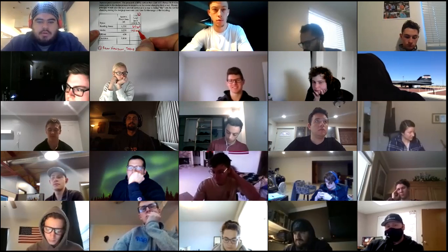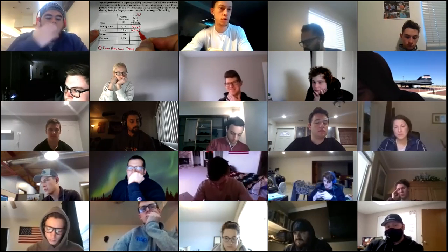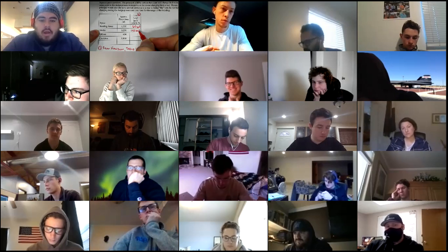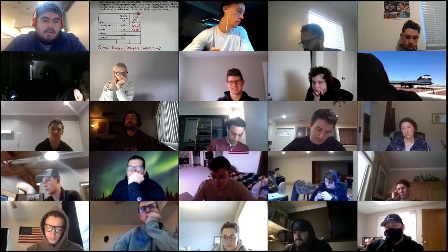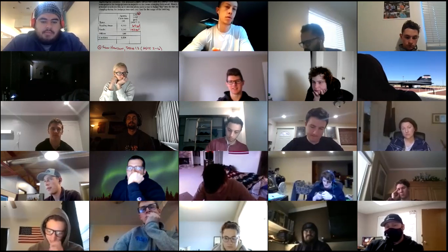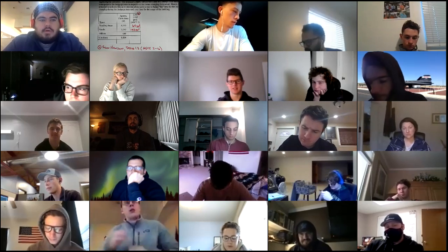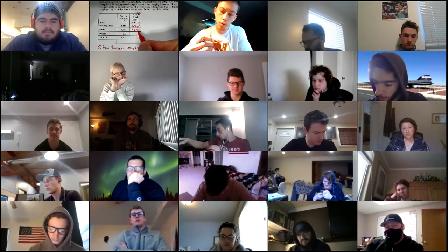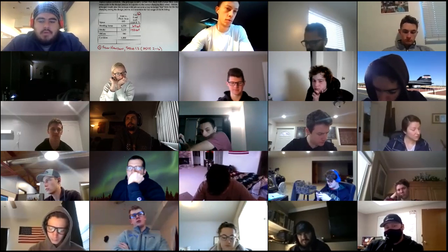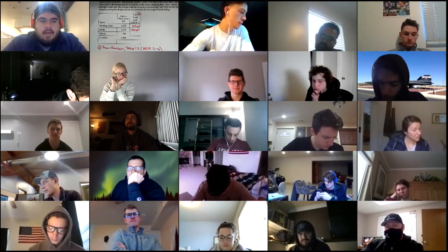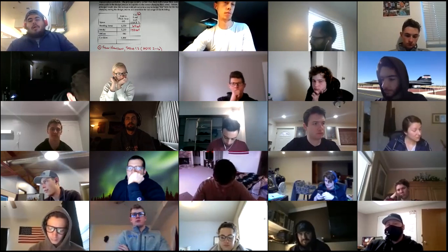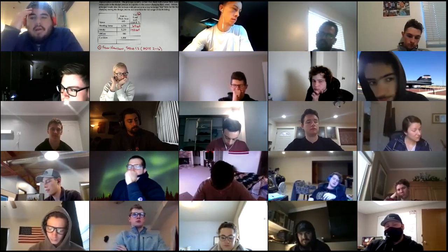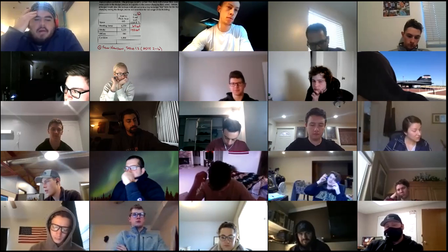Now, stacks that are fixed to the building, that aren't movable stacks, you've got big, heavy racks, multiple shelves, lots of books, lots of paper documents, and that's why that live load gets kicked up so high, because it's 150 pounds per square foot. And that superscript, which says you can't reduce that, relates back to this notion that, okay, wait a minute.